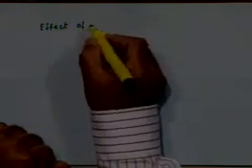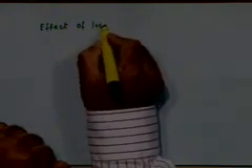We also call it the effect of loss of coherence. We are saying that the local carrier and the incoming carrier are coherent with respect to each other. By coherence, we mean essentially it's a term for indicating that they have the same frequency and the same phase, right? That's what we mean by coherent here. So if there is a loss of coherence, then there will be some undesirable phenomena taking place.